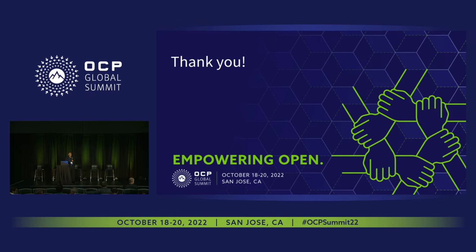How are you? El Ramirez here. Is it recommended nowadays to keep the RPM of the system of the fans at 70% limit, or below 70% RPM out of 100%, to be able in the future to reduce the acoustics? Okay. So I am not aware of any particular recommendation based on just RPM itself. I think it goes by what the acoustics disturbance levels or the vibration disturbance levels are. So if you're talking about very high RPM fans, then 70% might still be pretty high.